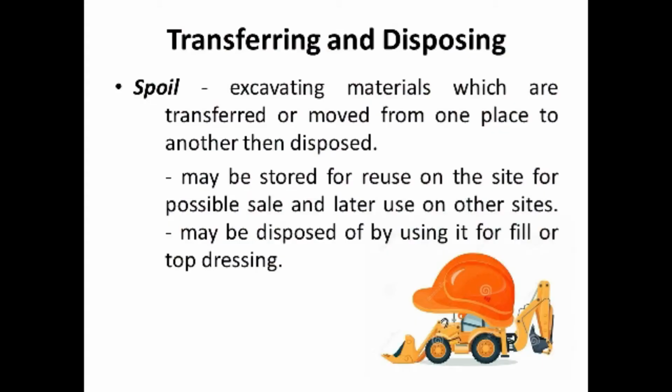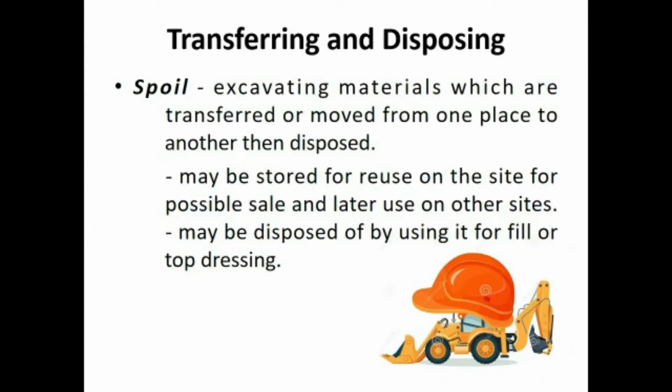In earthworks, we also have transferring and disposing. Here we have spoil, which are the excavated materials which are transferred or moved from one place to another, then disposed. They can be stored for use on the site or for possible sale and later use on other sites. It may be disposed of by using fill or top dressing.